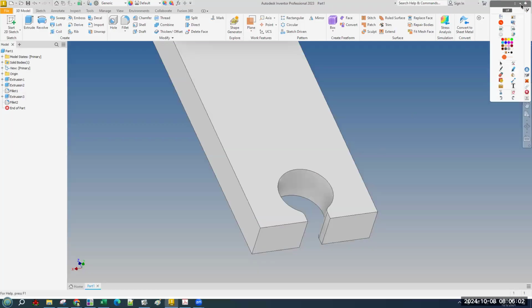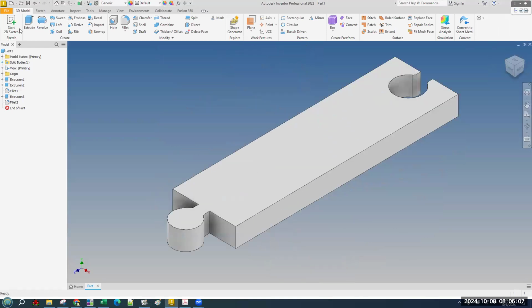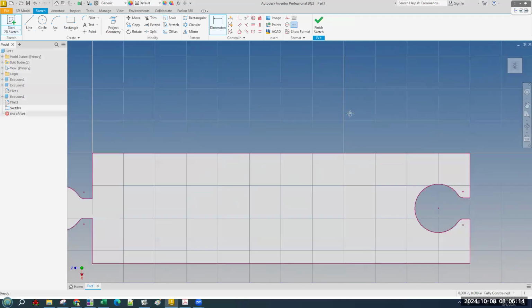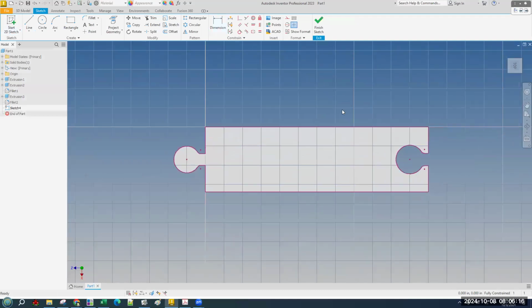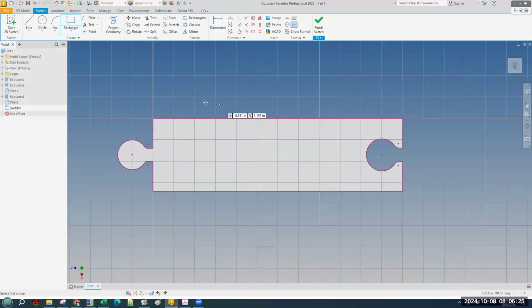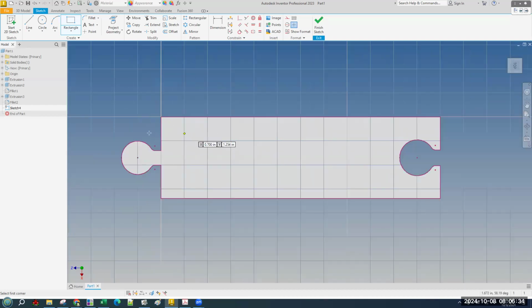Okay, so we're sketching on the top, and we just look at it from the house. Put a sketch on the top. And because both of these troughs are the same size, or the same cut extrusion, I'm going to do them on the same sketch and then do them in the same part feature. Okay, so our first rectangle is going to go from one side, soft snap on this edge. Make sure you don't get the center point. It will prevent it from being correct.